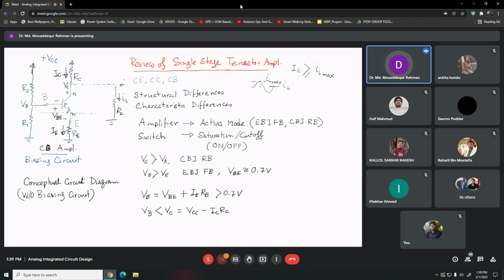What is the other requirement about voltage? Now, there will be output voltage, load current, and there will be output voltage or load voltage, whatever. This is also a signal voltage, right? Now, here you have the voltage VC, right? This voltage is AC voltage, and the voltage here is DC voltage, right? So basically in the amplifier circuit, you have both AC and DC voltage, because DC is needed to power up the transistor, and AC is the actual signal current or voltage that you are trying to amplify, right?